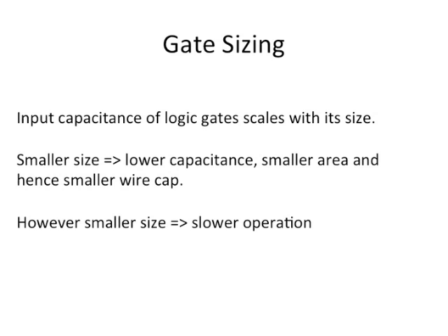Any other paths which are not critical, that means their delays are smaller than the delay of the critical path, you can actually slow them down. There is no need for them to be running that fast. You can slow them down by maybe sizing them smaller, and there are some other techniques, maybe using higher threshold gates and so on. So you are slowing them down so that you are saving some power, but not affecting the overall performance.